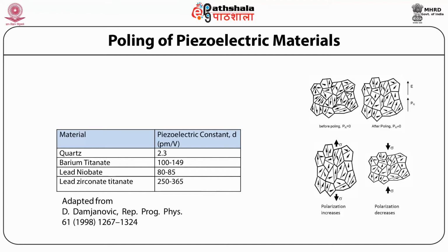Most ferroelectrics have to be poled to be useful as piezoelectrics. In the unpoled virgin state of the material, the ferroelectric domains of single polarization direction are randomly distributed across the material, and in such a situation, the net polarization would be zero. So the application of stress to such a material would not achieve any change in the net polarization, therefore making it useless as a piezoelectric.